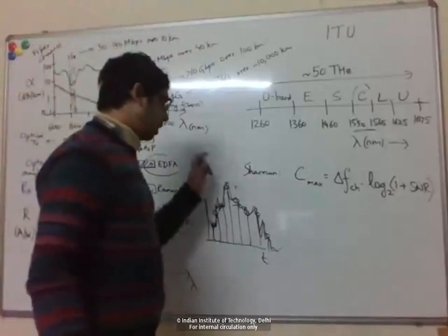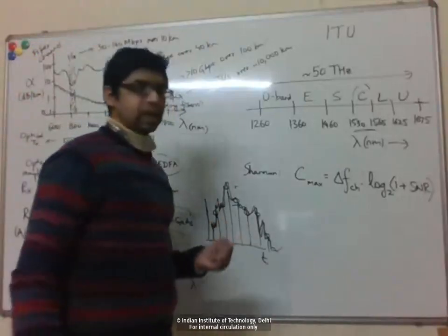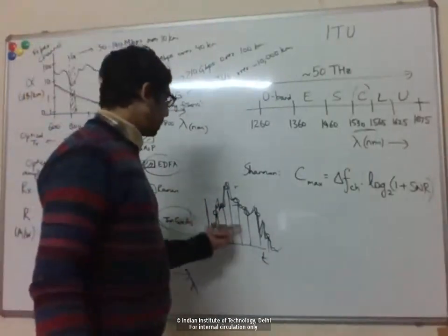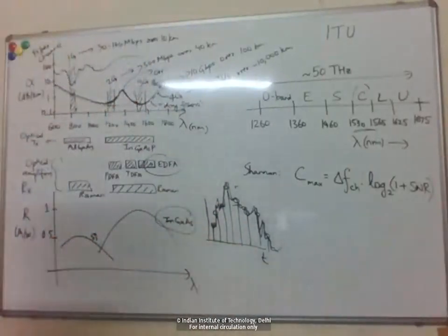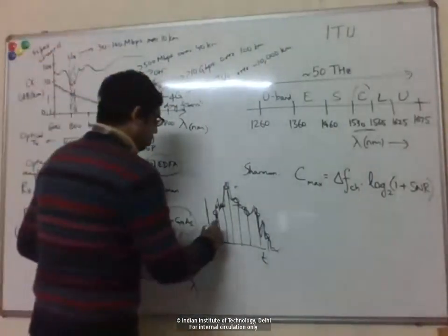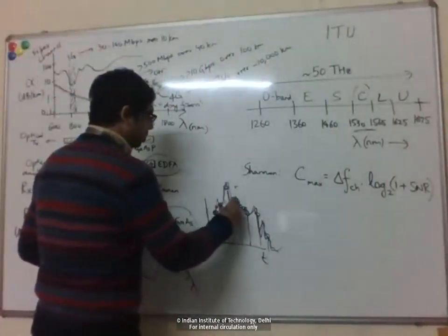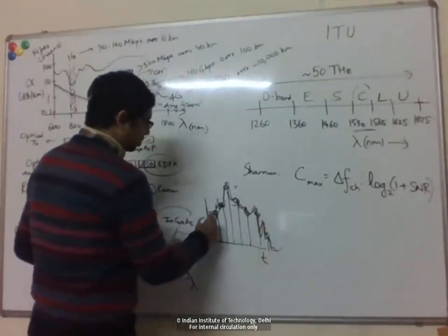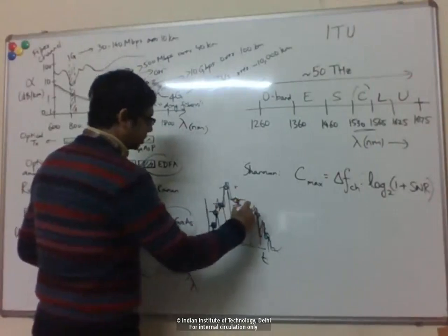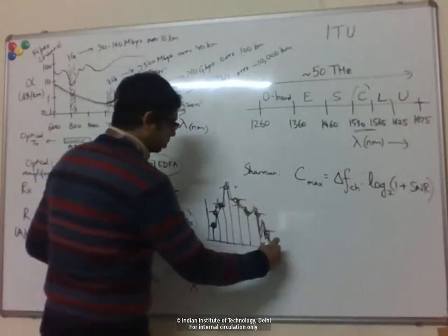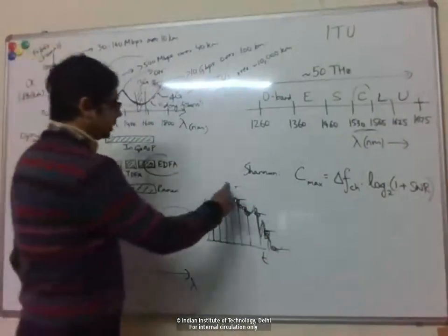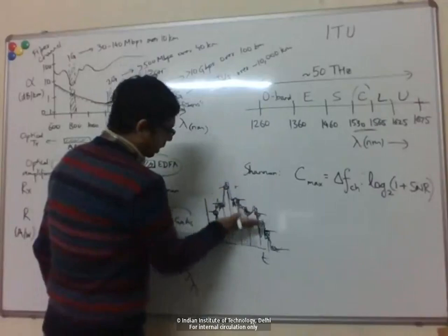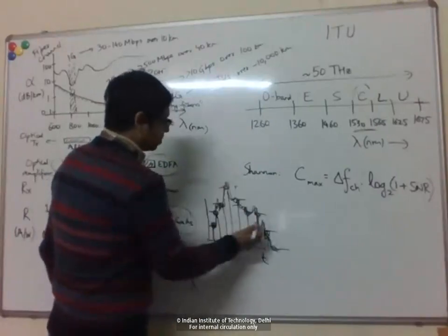And now again there are requirements on what should be the sampling rate, right? So there is this Nyquist theorem that you need to sample at a rate at least twice the maximum frequency of the signal, right? So anyway, so you sample the signal, so you get a set of points in time, and then for these points, now you quantize them, right? So you convert them into numbers, and the quantization that you can do, so you can have any number of levels that you specify, right?